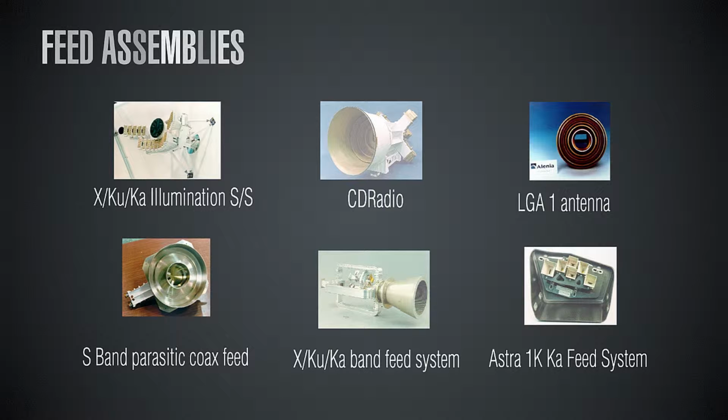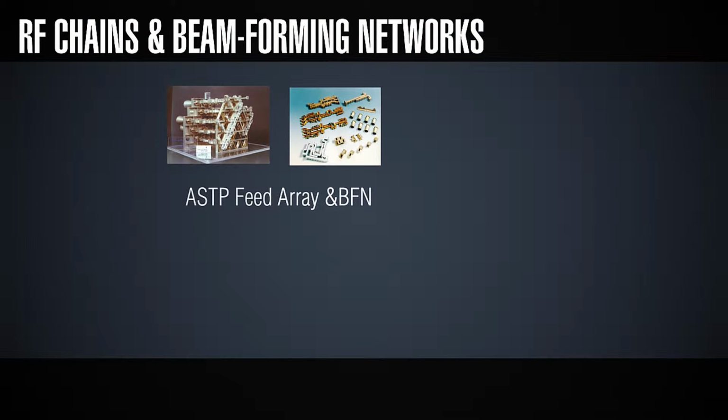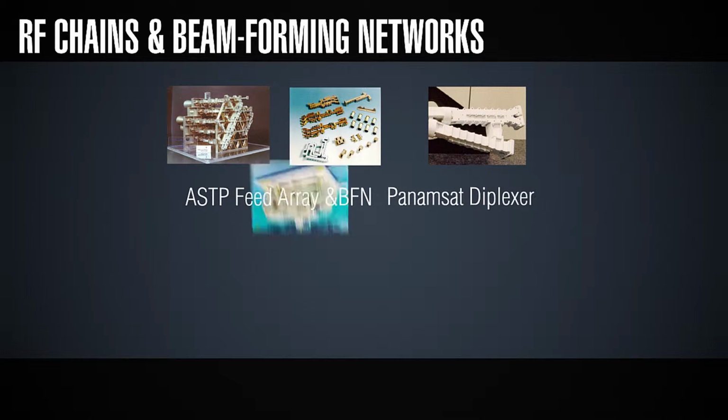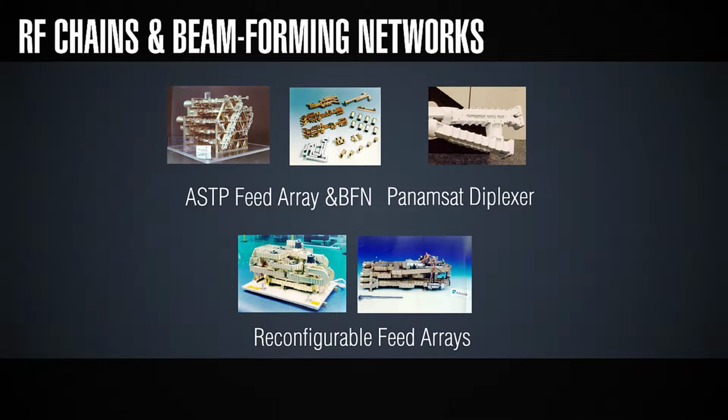And we also mentioned already the need for beamforming networks. Beamforming networks being networks where you divide the signal and you feed an array of feed elements with proper amplitude and phases, with the objective of creating either a multi-spot type of coverage, or combining several spots together to create a shaped or well-contoured beam over the area to be illuminated by the antenna.